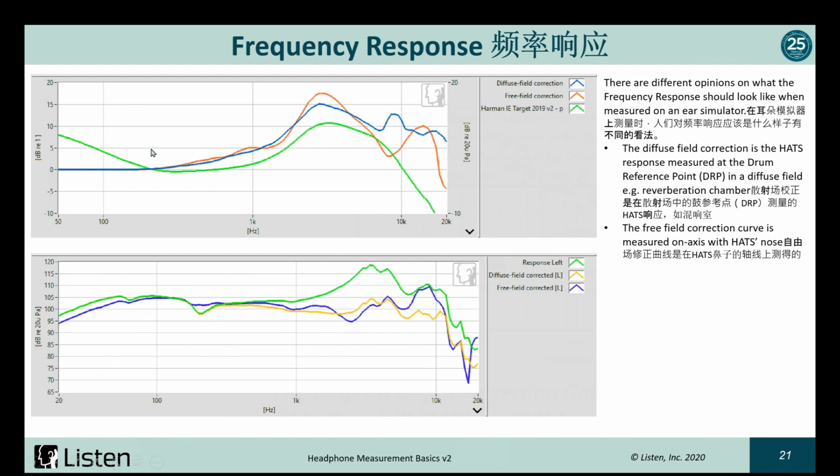But basically, you'll notice that at low frequencies, there's this boost, and it's generally because we're used to listening to loudspeakers in a room, and typically the loudspeakers are in the corner of a room, so they inherently get this low frequency boost from the room, you could say room reflections, or just the corner loading of the loudspeaker. So as a result, most people expect that same bass boost in their headphones. And that explains why a lot of times headphones don't sound like they have as much bass.